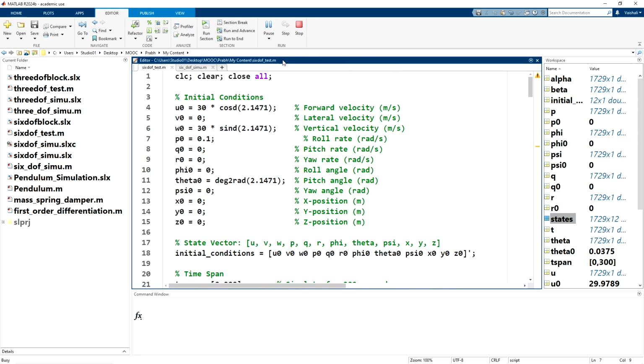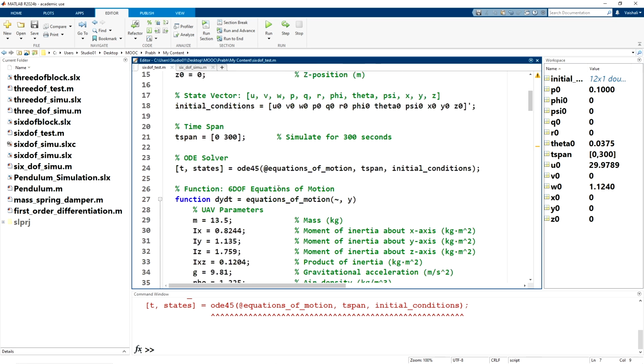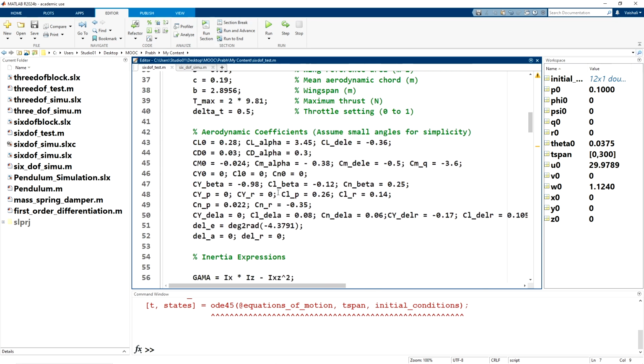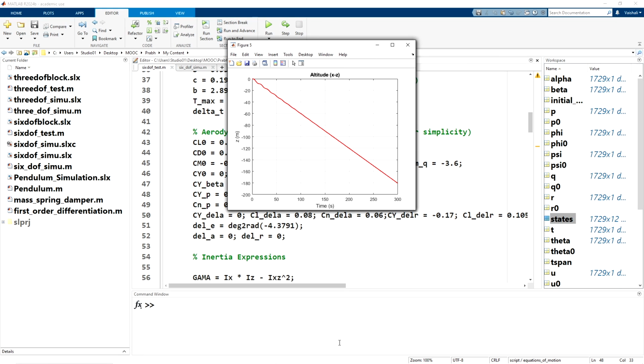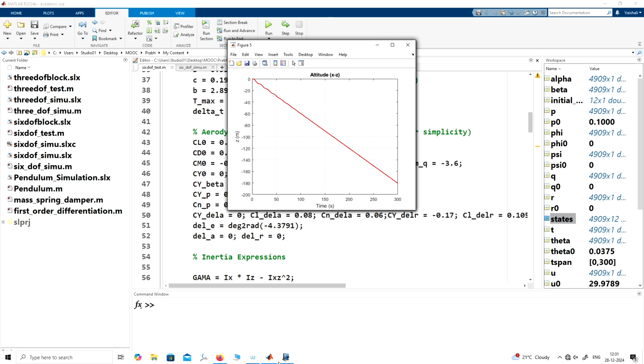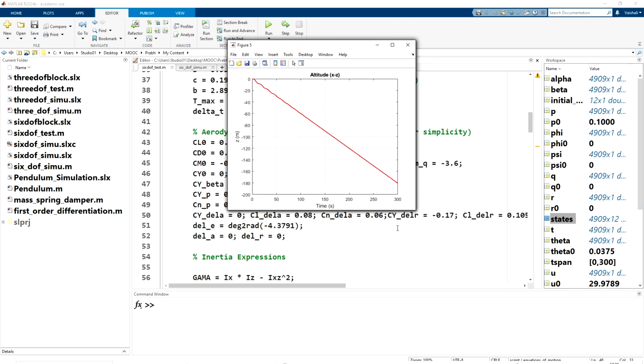I am stopping this simulation and then I check it with CLP, changing it to minus. Let me put it as minus over here and run the simulation with the disturbance in the lateral directional coefficients. So here we observe the aircraft returns to its equilibrium position in finite time. All right, so that's the significance of CLP.